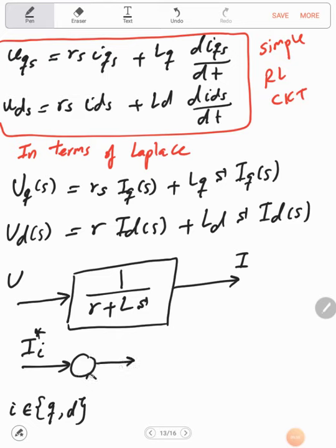Now here we should compare it with the actual current. Now in general we'll use the most famous controller, which is the PI current control. The output of the PI current control is the voltage, which here is the U i, and remember i can be Q or D.